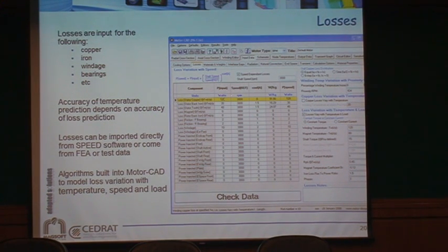And all of those values are defined for a certain reference speed. With this reference speed, we can apply a formula that will compute the power losses at any speed. And why is this important? Because we want to be able to do the duty cycle. If we want the duty cycle, we need to be able to compute the losses at every type of state. Here is the current distribution in the copper.